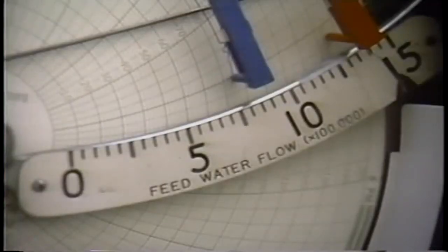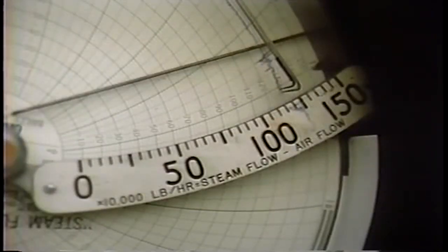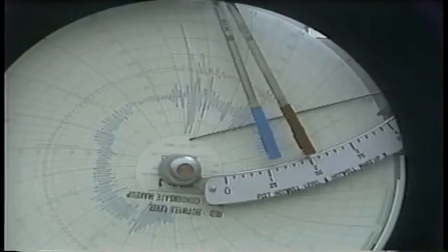A boiler tube leak can occur anywhere there's a boiler tube. An operator usually has a number of ways of knowing that a tube is leaking. During a boiler inspection, for example, the operator may hear a hissing sound coming from the boiler in the area of the leaking tube. Depending on the location of the leak, an operator may be able to see the leaking tube when making a boiler flame observation. Instrumentation in the control room may also tell the operator that a tube is leaking. A difference in feed water flow to the boiler and steam flow leaving the boiler is one indication of a leak. Another is an increase in the makeup rate for the boiler, as indicated by this pen on this recorder.